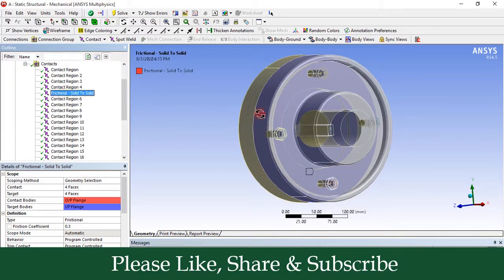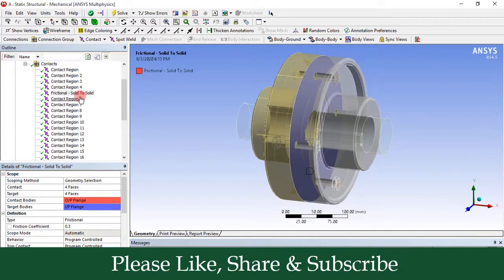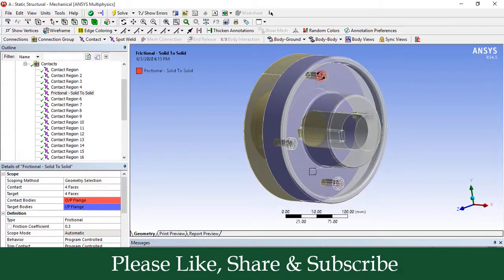Only the contact between output flange and input flange is taken as frictional, because if these 4 bolts get sheared off, if these 4 bolts fail because of the shear stress, then there would be chance of rotation of the output flange with respect to the input flange, and there would be frictional contact between these 2 flanges.